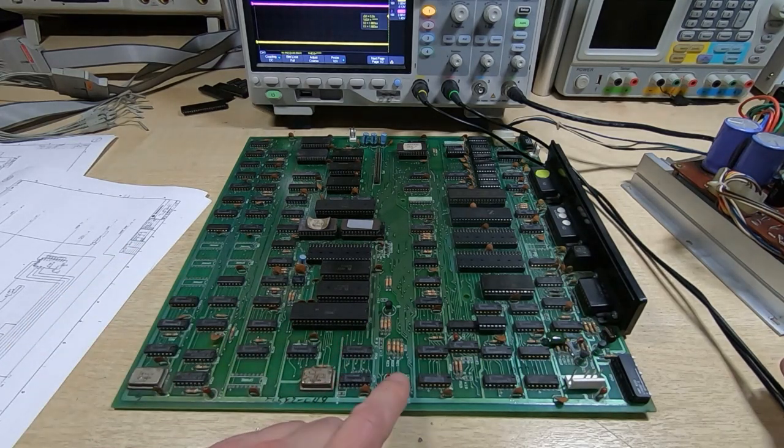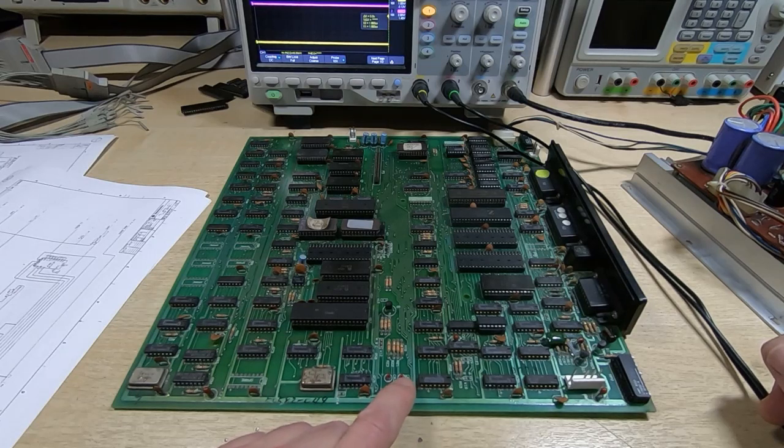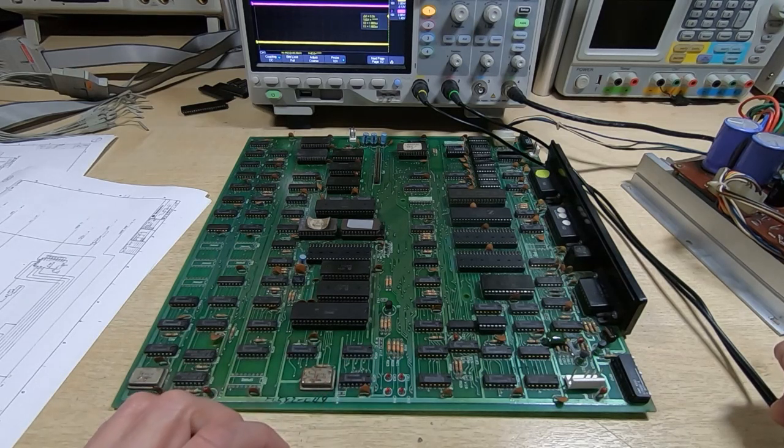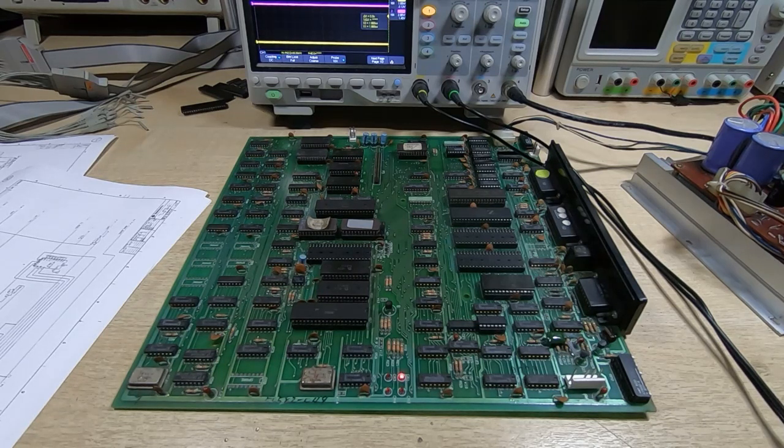If you recall, when we turned it on before, the first test LED was coming on for half a second, and then it started flashing to indicate a fault. So we'll turn the board on, keep an eye on the LEDs. Looking more promising already. The test is still running, and it's moved on to the second test, and that is now failing.